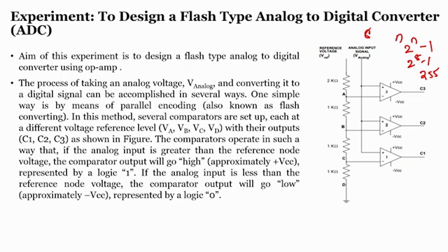So how can we do it with flash type ADCs? It is almost impossible. Because of that complexity, flash type ADCs are generally used only for low bit conversion. Also, the cost of each comparator itself is very expensive. As a result, 255 comparators will be very expensive.